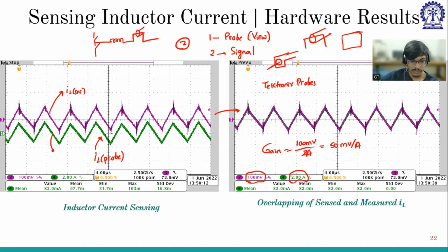But now we are passing it through RSH, and if you see, this RSH has some small impedance. If your pole is not exactly cancelling the zero, this inductance might create some spike, right? If it completely gets cancelled, then we get the scalar gain. But if you do not get the exact cancellation, then there might be some inductive effect, which might lead to this kind of spikes.